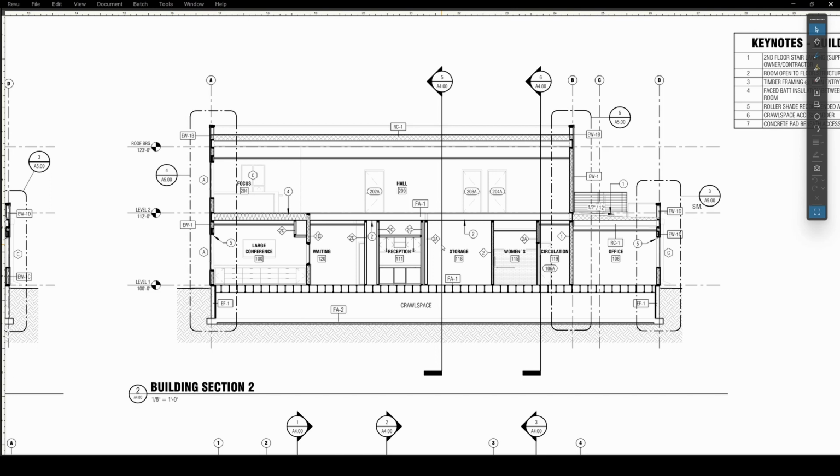And finally, here's another building section that I did recently for a construction office here in town. Here you're seeing the levels, again, the datums, the horizontal grids, section callouts for perpendicular sections, room tags labeled. And then this is also very important. You're seeing the tagging of individual floor and roof assemblies. RC was an indicator for roof construction. FA was floor assembly. And then you're seeing the room tags and their relationship horizontally as well as vertically of what that section looks like.